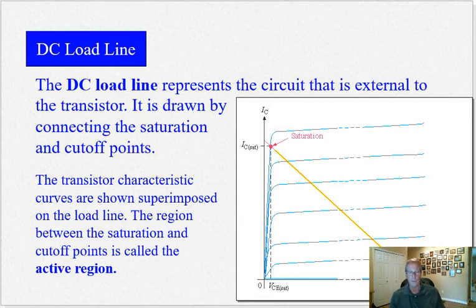Corresponding to the beta. Okay, so you have your collector current, which is in milliamps usually, and the base current, which is in microamps typically, and that's how the amplification occurs. But don't forget these 2 points: saturation and cutoff. Cutoff is when the transistor is completely shut off, and VCE, collector emitter voltage, equals the collector power supply, so it's completely open. And then the other end, where the collector emitter voltage is at a minimum and your collector current is very high.